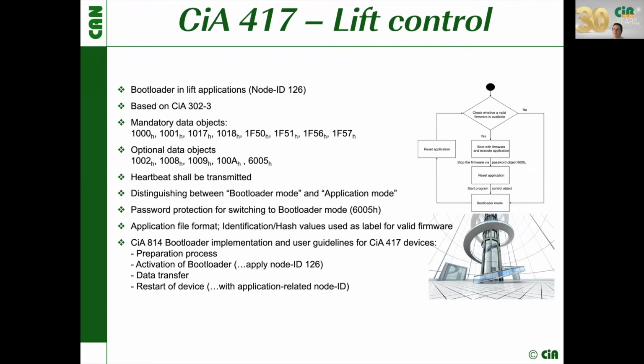I have a write protection at object 6005. And there's a file format specified with some identification labels and hash values, so that a device that shall be updated can evaluate, is this a valid firmware?